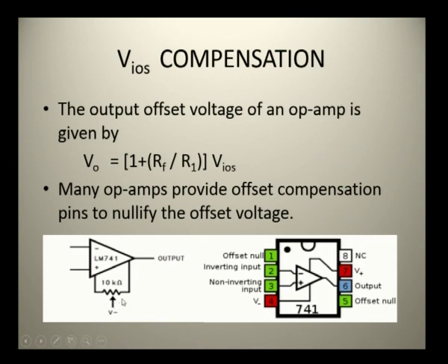So if you change the position of the wiper, accordingly the voltage applied to the first and fifth pin changes, and this voltage is going to nullify the output if the input signals are 0. So we have nullified the effect made by the input bias current, input offset current, and output offset voltage. Still there will be some output even though the input signal is 0.